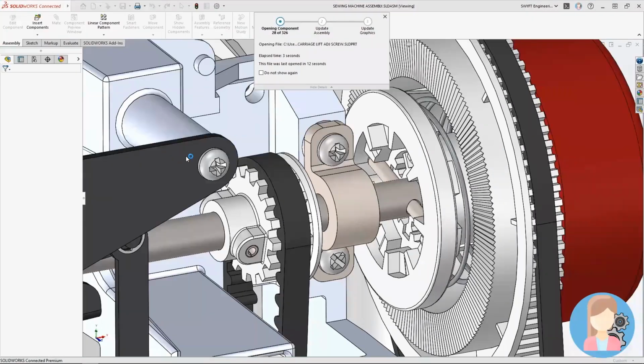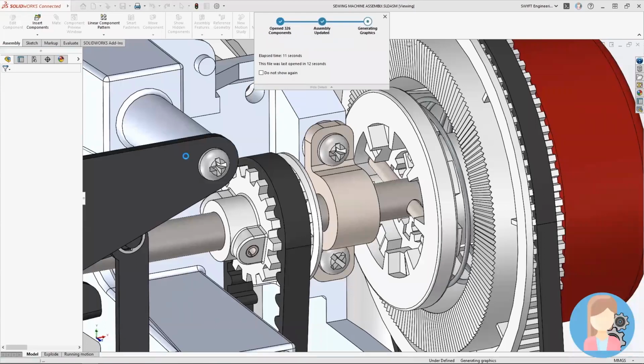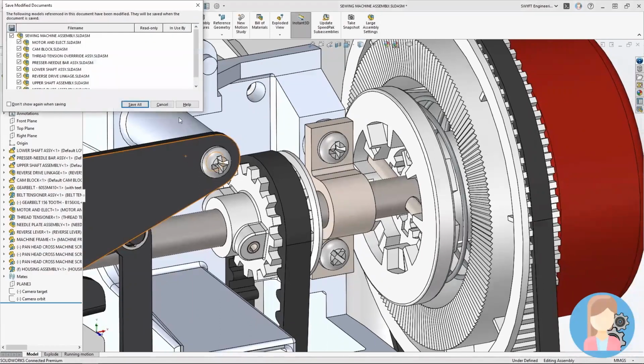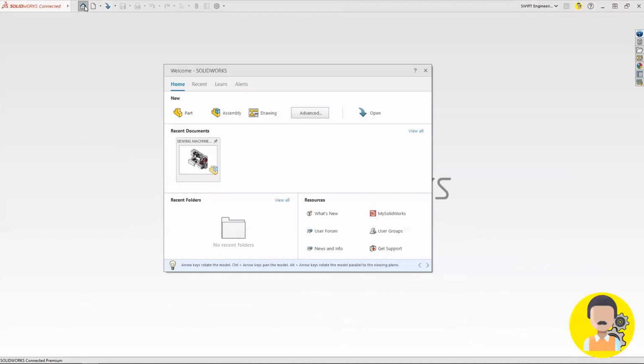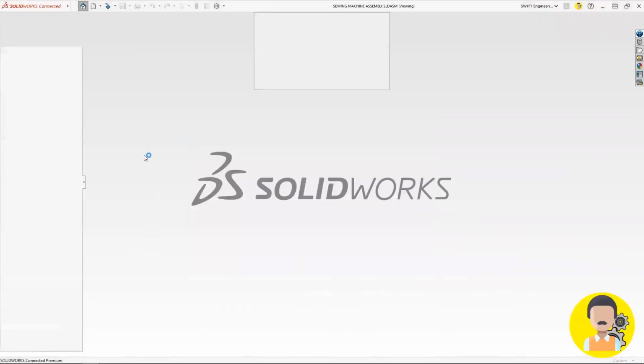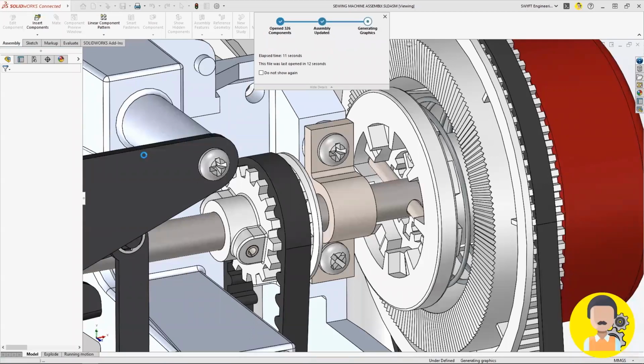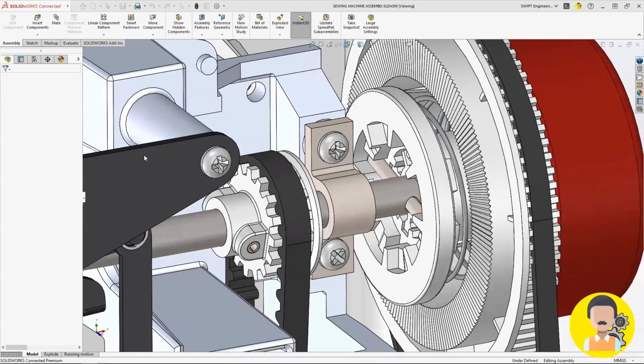But in this case, now when she opens this from the location here, it goes through that search routine. You overwrote the file that was there. Since it has the same file name, it will pull that right in, just like it did last time. But in this case, it's pointing to the right location that Lucas still has shared access to. So switching over to his case, when he opens this up, we'll go through and update. You see it in the preview because it was saved with the preview, but by the time the graphics are updated, it will be connected to the right part for everyone.